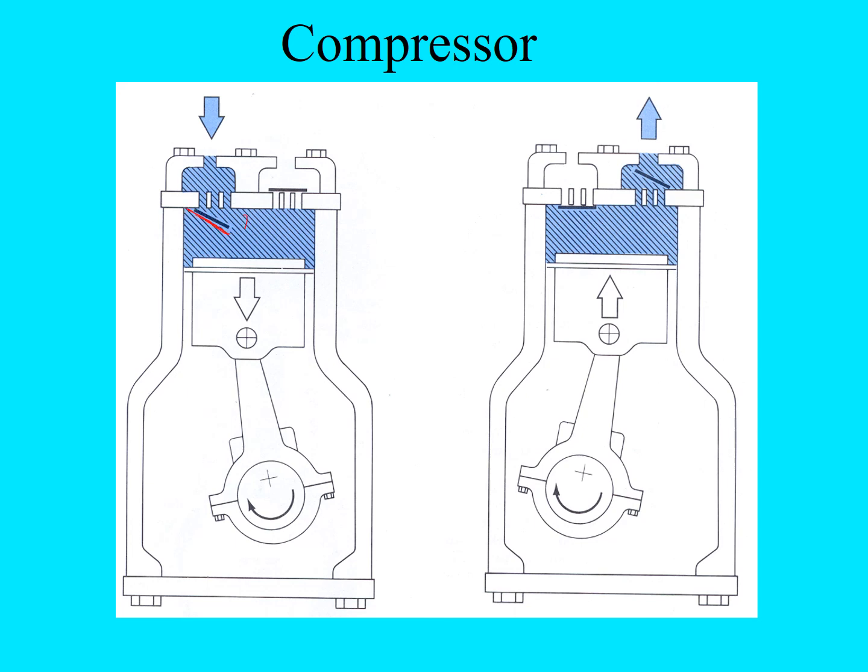So that opens and allows the refrigerant to be pulled into the chamber. The reed valve up here is closed. So that would be like the intake stroke, and then when we push the refrigerant out, this reed valve closes and this one pops open and allows the refrigerant to flow through. So the refrigerant's not being compressed inside the chamber.